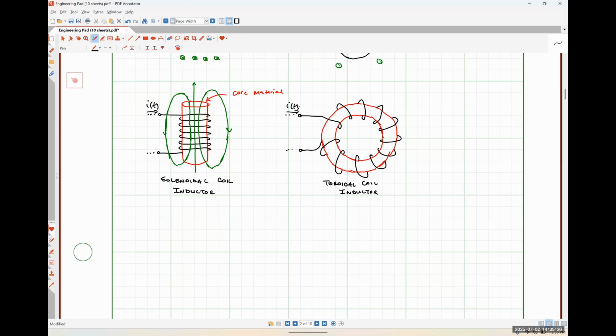at all. But essentially, because it doesn't have any air gap, it shouldn't have any losses. So what we'll find is that our magnetic field lines still get confined, so that we have lots of coils, so that we have large amounts of magnetic field in our structure. But now our magnetic field just circulates around inside of this core material, and we don't have any losses to deal with. Okay. So this is a better inductor for most applications, loses much less energy out into the air.